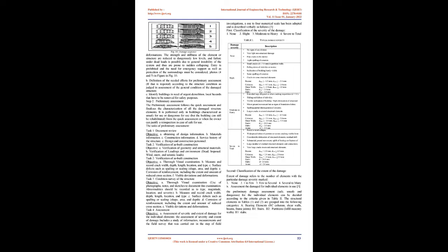The preliminary assessment follows the quick assessment and finalizes the characterization of all the damaged structure elements. It is performed only in buildings characterized as unsafe for use or dangerous for use, but the building can still be rehabilitated, from the quick assessment or when the owner can justify a re-inspection in case of safe for use. The tasks of preliminary assessment.